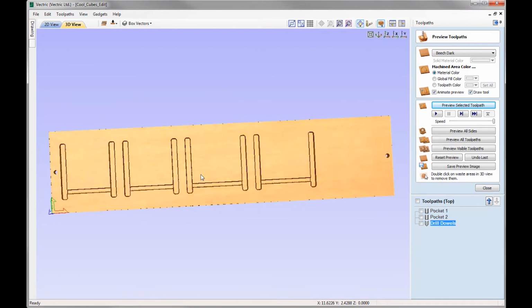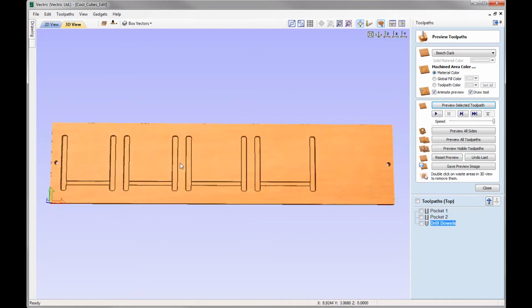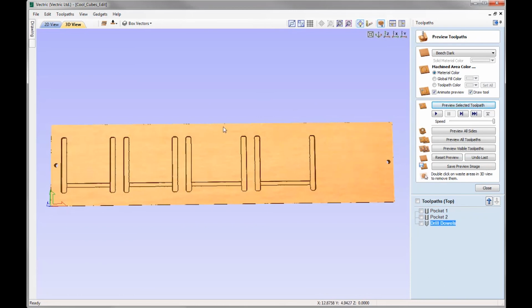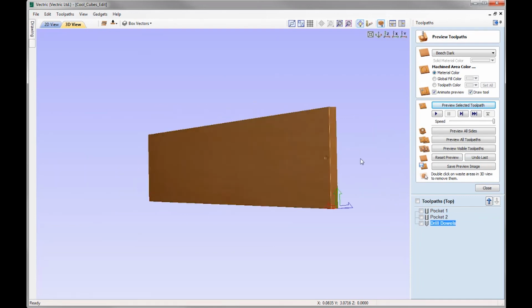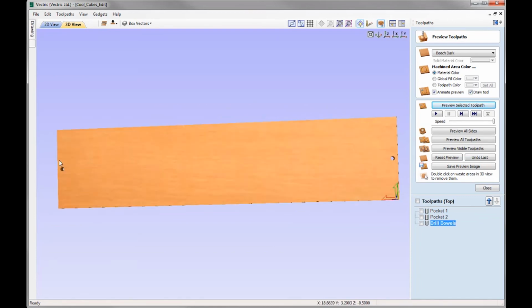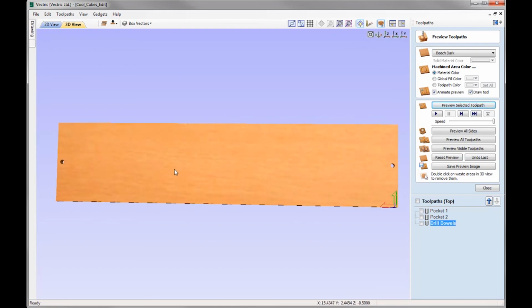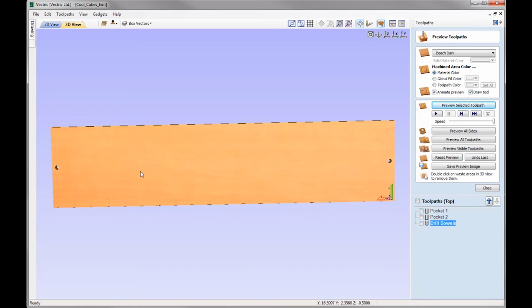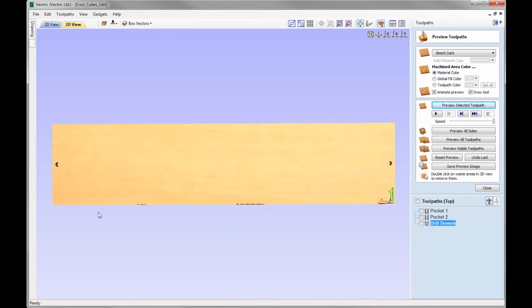So at this point, what we'd do in terms of the physical setup is we'd take this material block off of our machine bed and we'd insert the dowels into the holes that have been drilled into the spoil board. And then we'd take our material and flip that over, and then position that and align it to the dowel holes where we'd secure that in place. And because we've aligned it to the dowel holes, we know that our XY coordinates are going to be aligned with each other. And then we'd look at running the toolpaths for the bottom side.